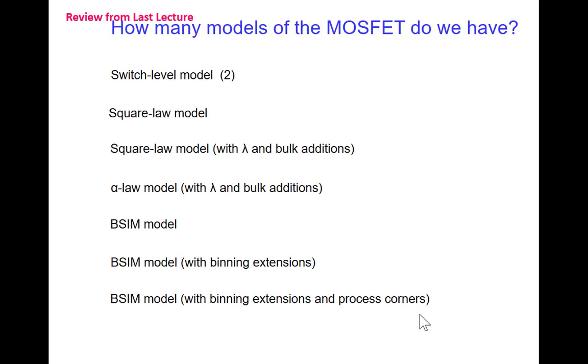And then they get empirical models, they measure model parameters for those transistors. If you want a device that's wider, you put 2 of them in parallel. If you want a device that's longer, you put 2 of them in series. Does that make sense? Instead of giving you complete control of the dimensions, they have a small number of devices you can put in parallel or in series. And that circumvents this issue of how do we get a model that accurately characterizes the IV characteristics when you change the dimensions of the device.